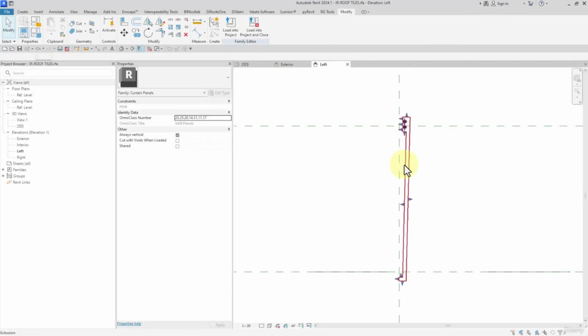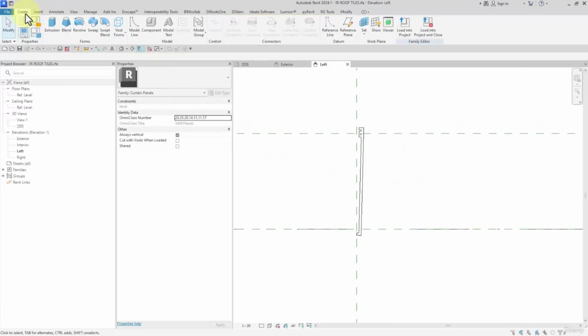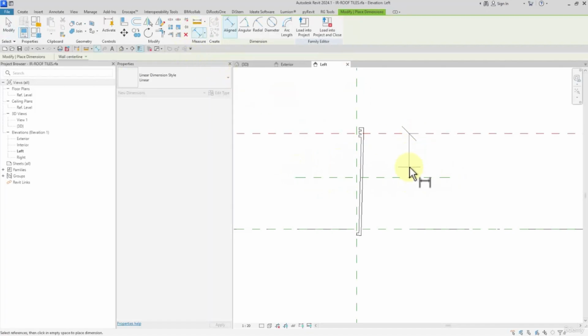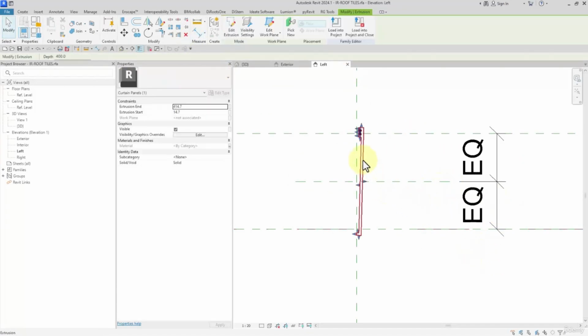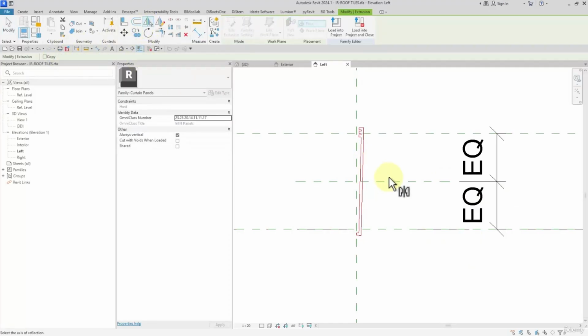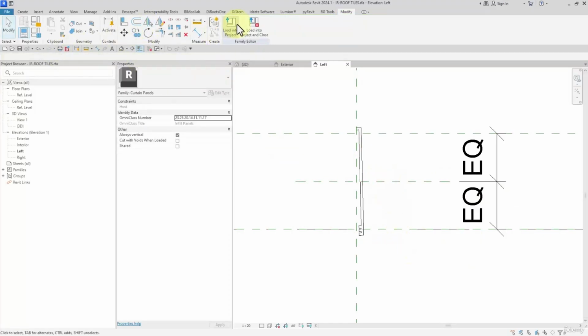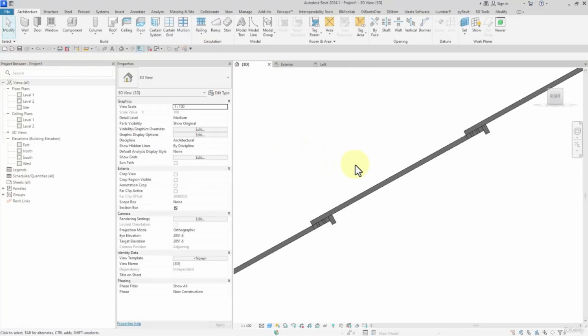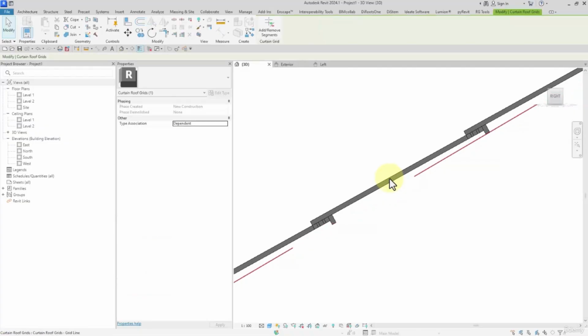So again we should get back and then selecting the model, and I want to draw a reference plane at the center, at the midpoint. Then I equalize both sides like this way. Afterwards, mirror pick axis, unchecking copy and mirror it. Again, overriding the existing version. Watch this. Better. After this, I press down tab to select one of them.